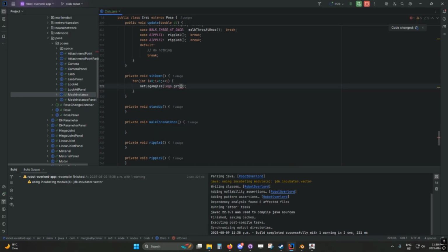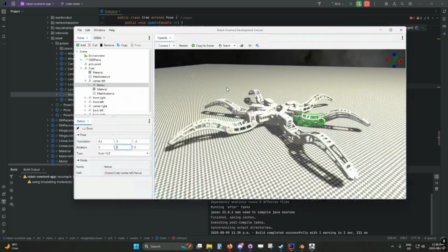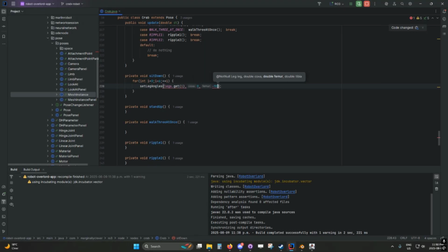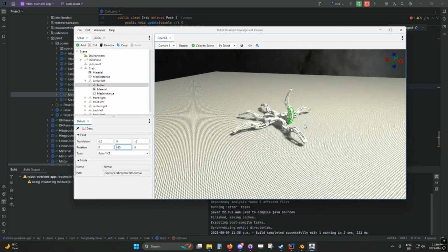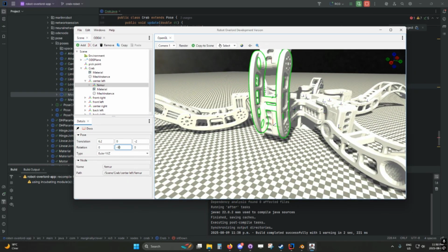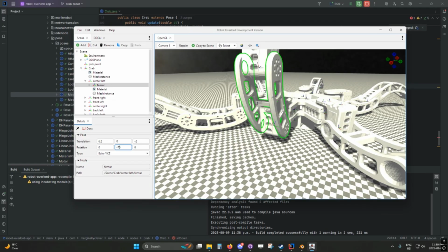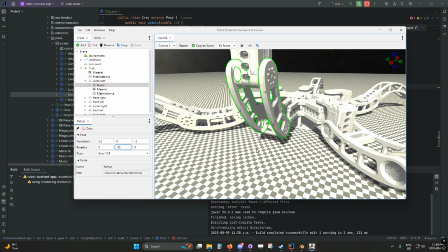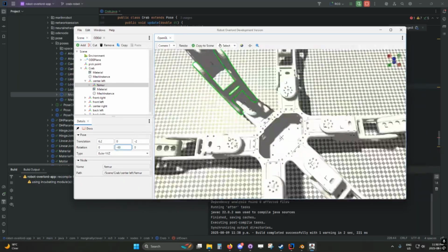So okay, this is legs get I, and then we give it 3 values. So that would be initially 0, and then initially this value should be minus 40. What do you want this to be? Minus 90? So like this would be the homing position, right? Yeah. Okay, 90. Wait, actually, let me think. Can you look at the little oval brace you were talking about? Because that can't overlap with the plastic, obviously. Right there, you see? That's too far. I wanted it as close as possible to touching the thing. Let's say 60. Wait, on my model, it goes up past 90.